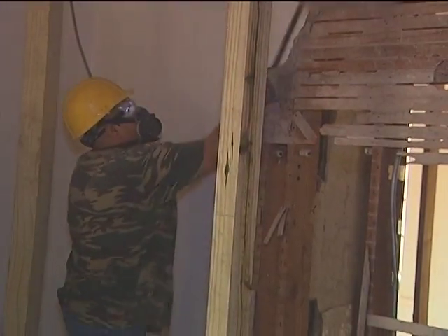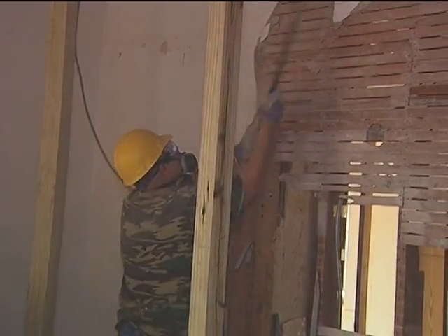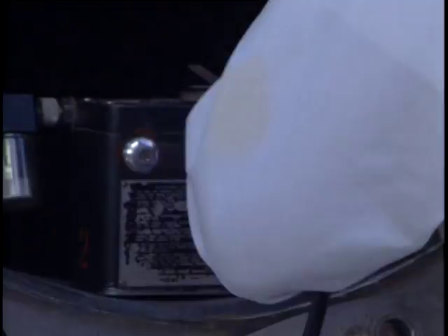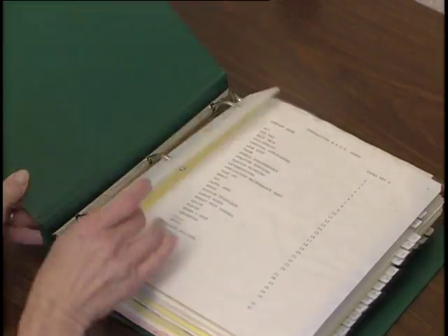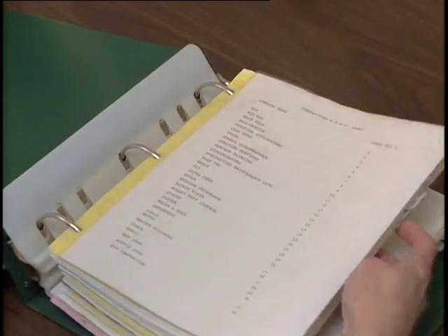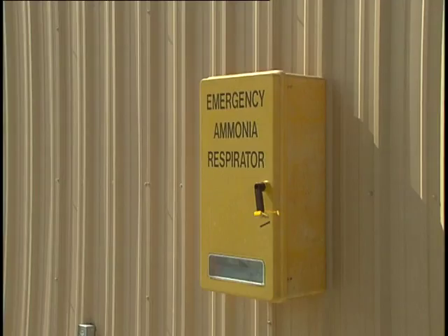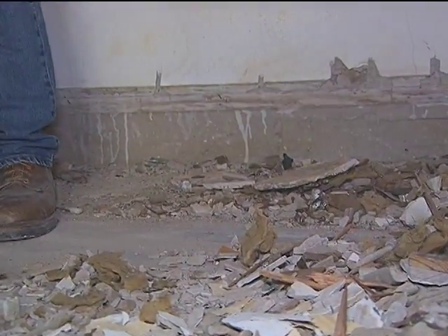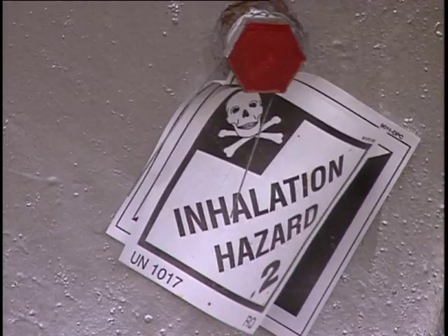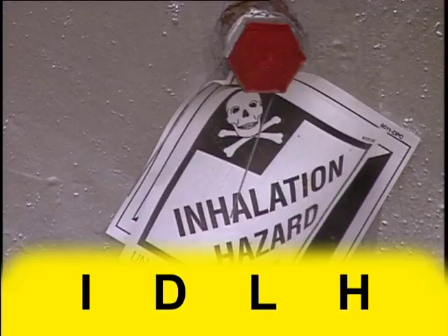When employees are exposed to respiratory hazards and/or are required to wear a respirator, an exposure assessment must be made. Employers must first identify and evaluate the respiratory hazard or hazards in the workplace. Employers must make a reasonable estimate of the employee exposures anticipated to occur as a result of those hazards, including those likely to be encountered in reasonably foreseeable emergency situations. When the employer cannot identify or reasonably estimate the employee exposure, the atmosphere should be considered immediately dangerous to life or health, or an IDLH atmosphere.